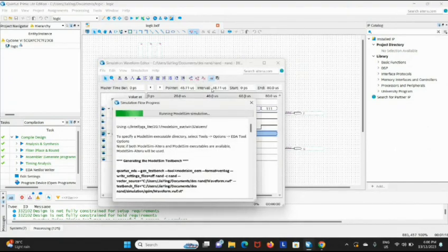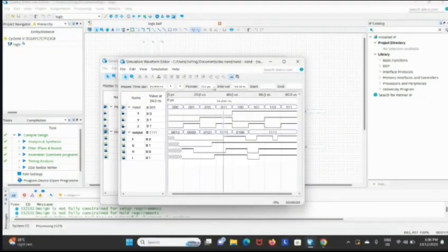As mentioned just now, the timing simulation of the NAND connection also differs slightly from the functional simulation, and it also has some difference from the timing simulation of the simple logic gate. For example, taking output F, the delay time shown by the NAND network is 4.496 nanoseconds. The calculation method is the same as before: 34.496 nanoseconds minus 30 nanoseconds, so we obtain 4.496 nanoseconds of delay time for the output of F. And for the output of G, the delay time is 7.28 nanoseconds.